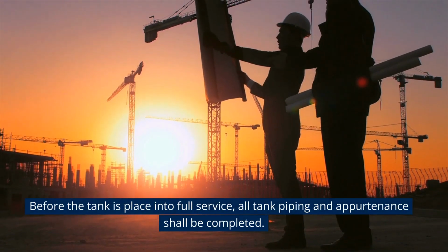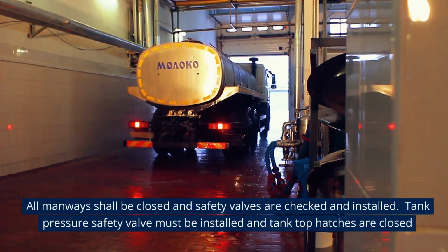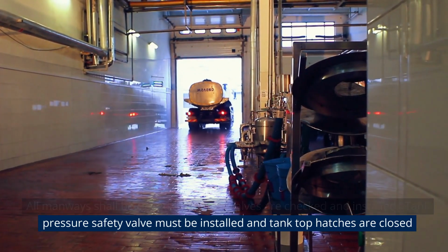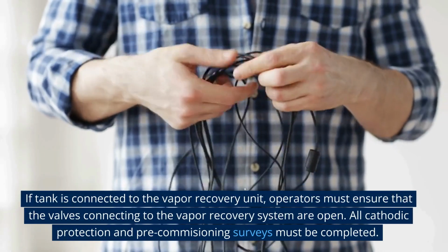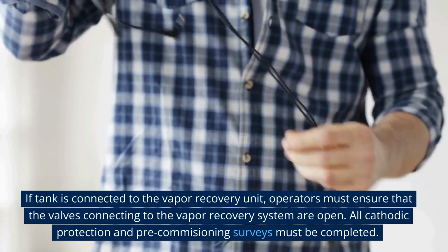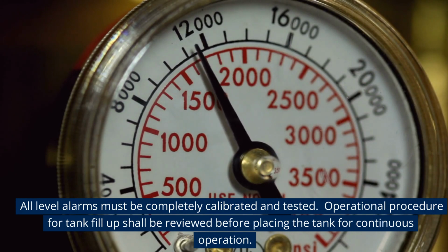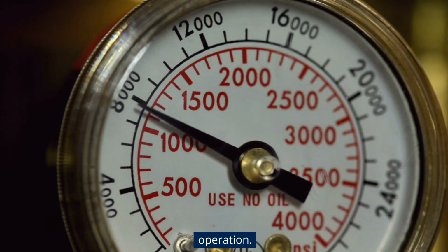Before the tank is placed into full service, all tank piping and appurtenances shall be completed. All manways shall be closed and safety valves checked and installed. Tank pressure safety valve must be installed and tank top hatches closed. If the tank is connected to the vapor recovery unit, operators must ensure that the valves connecting to the vapor recovery system are open. All cathodic protection and pre-commissioning surveys must be completed. All level alarms must be completely calibrated and tested. Operational procedure for tank fill-up shall be reviewed before placing the tank in continuous operation.